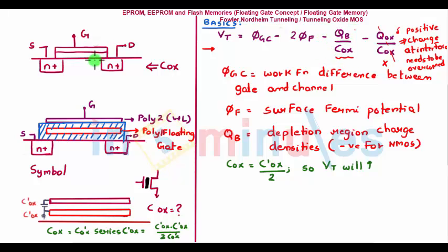Remember that. Now in a normal case, I have oxide capacitance as COX. In case of a poly gate, my COX would reduce by a factor of 2. Let's see how. This is my normal gate. This is my poly gate. Between my normal gate and my poly gate, there will be a capacitance. Let's call it C-OX, because there is an oxide which is present, right? You can see that.